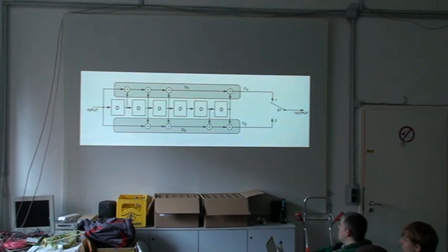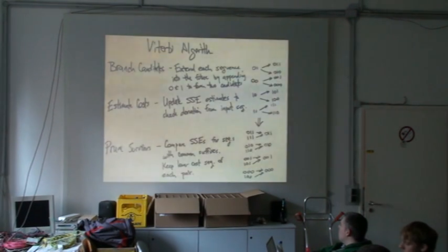Originally this is a problem that is exponential with the length of the input stream, but in the 60s a guy named Andrew Viterbi pointed out, no, it's not exponential with the length of the input stream, it's only exponential with the length of the delay line. It's only exponential with the size of the shift register. So here's the Viterbi algorithm. This is usually not the way it's presented in engineering texts. There are 3 steps.